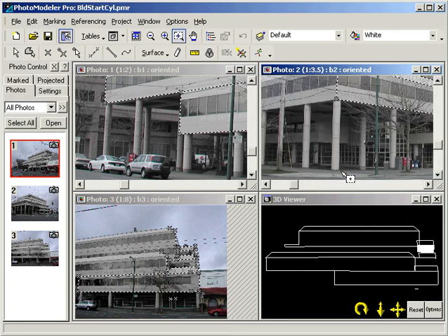To mark these poles, we use the Cylinder tool. We click the Cylinder tool from the toolbar, and our cursor changes to Show Cylinder mode. The Cylinder tool is similar to the Edge tool in that it is used to mark along the edges of the cylinder object, and the endpoints are not important. With the Cylinder tool, we mark the 2 visible edges of the cylinder.